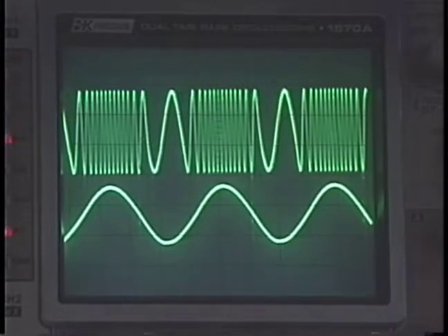Now let's take a look at frequency modulation. This is the technique used in FM radio transmission. An FM radio tuned to a station at 100 on the dial is tuned to a 100 million hertz carrier signal. On the oscilloscope, we see the amplitude is not changing. Instead, the frequency of the carrier signal varies according to the amplitude of the information signal.